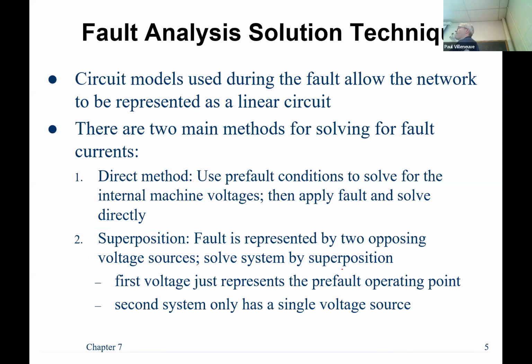Yes, sir. So when you're talking about faults, would it be like any location where fault is possible? Well, that's the thing. Any location is possible for a fault, right? You have to assume that a fault can happen anywhere on your system. It is not a perfectly 100% reliable system. And because you have to isolate the fault, right? Imagine if your devices weren't rated enough to actually interrupt the fault, you'd keep feeding fault current for extended periods of time. Fires, damage, people would get hurt. That's part of the problem with inverter-based systems because they have so little fault current. You could have a fault on a system and you can't even tell.